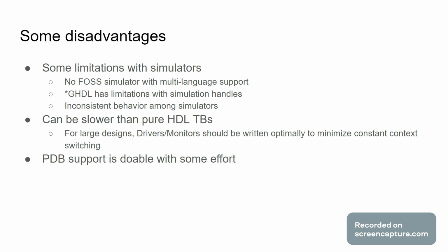But if you're using either Icarus or GHDL, in my experience, I've used Icarus, GHDL, and Questa. In terms of using cocotb, those three simulators are the ones that I have extensive experience in. Icarus is a Verilog simulator. It works really well, but it only does Verilog.